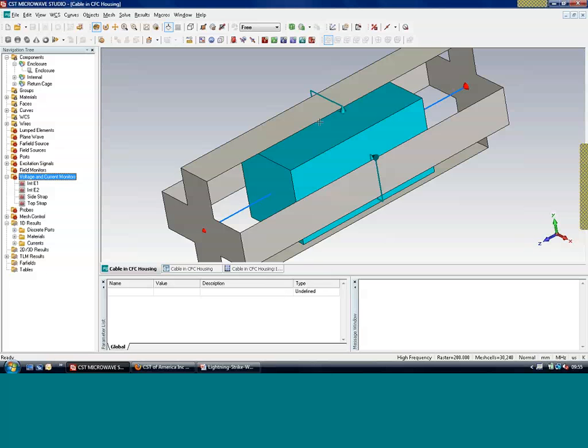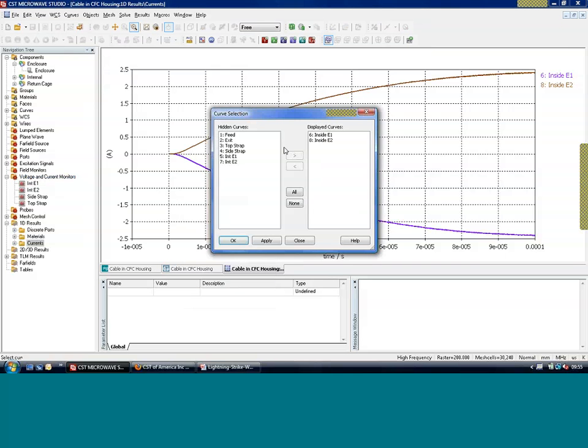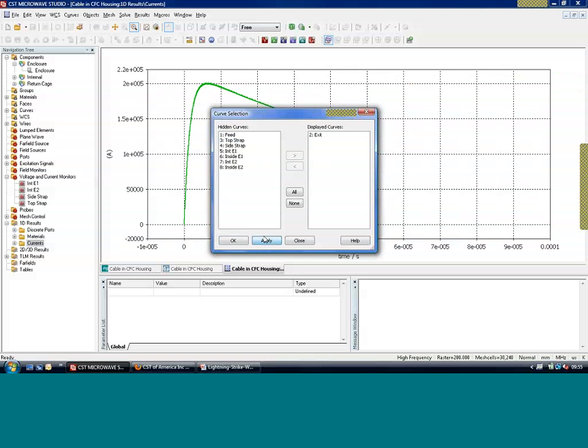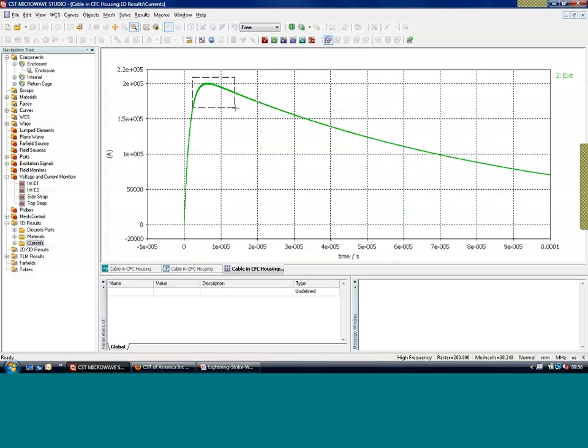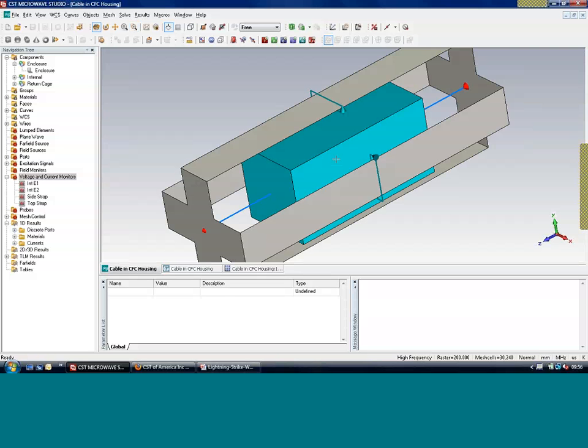It might depend where your oscillations are occurring. If you actually look at the current at this point here, you do see a little bit of oscillation on the current. So if I just show you that one on its own. Let's take those two off. Let's just put the exit current on. I'll zoom in on that area there. So there's a little bit of oscillation here. To be honest with you, I've not looked into the detail about that yet, but my suspicion is that it's a resonance effect of the length of the cage here, because we're just seeing a slight ripple there.